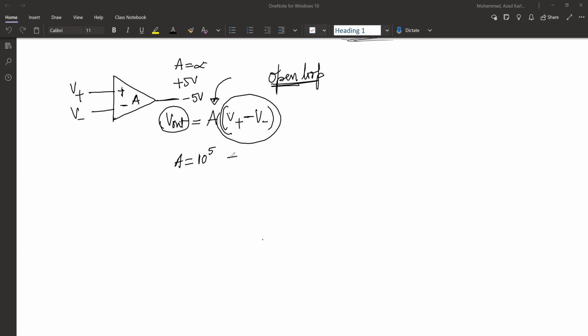And this is still with ideal assumptions. The ideal assumption is that the op-amp has a very large gain, which is constant irrespective of the frequencies you're operating at, correct? So if I just ground this terminal and give a sine wave input, I'm going to get an output which is 8 times the gain, 8 times whatever sine wave I give here. So let's say 2 sine omega t is what I'm giving. We'll just get 8 times 2 sine omega t.